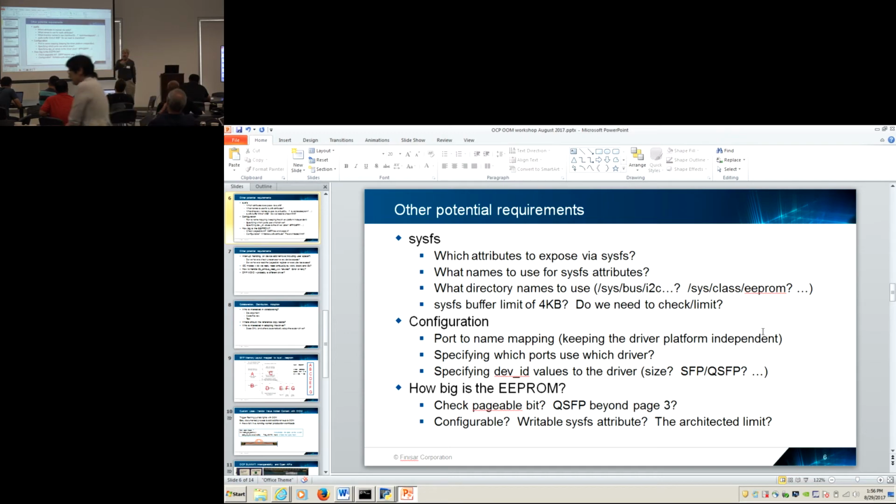And anybody else with an opinion, feel free. But this is just one of the silly little things I've got to figure out in the driver. So the problem is you're using it as an EEPROM, which is a flat memory, whereas what you are doing is at the end of it there are pages, and the page selector selects the page. Yeah, but that works. The driver handles that. The driver goes all the way to the end of the pages. But it's shown to the Linux system as an EEPROM, which is a flat memory. Yeah, which it should be.